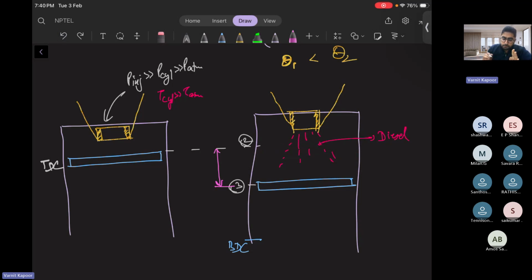So at point 3, this is the volume VF, which has been covered, for which the fuel was injected. And at point 3 the temperature is almost greater than T of self-ignition. And at point 2, the fuel started burning, so self-ignition was almost equal to T of cylinder, reached during the compression.